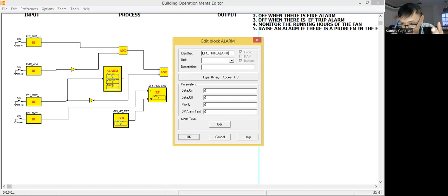Now we set the trip set point to around 2.1, 2.2. So if the motor is drawing current more than its full load current, then it should trip. That is the purpose of these overload relays, to prevent further overheating of the motor winding, because if you do not provide any protection there, eventually the motor windings might burn. So this is the importance of the overload relay.